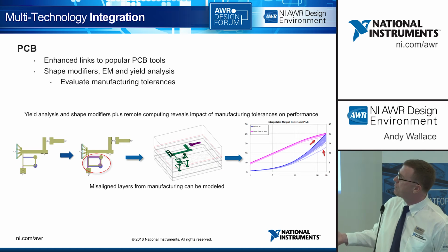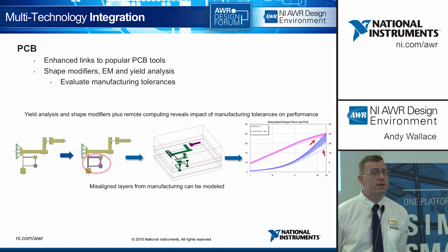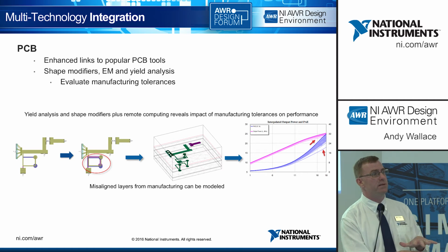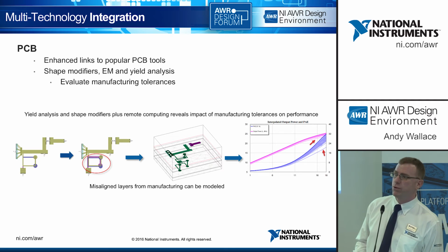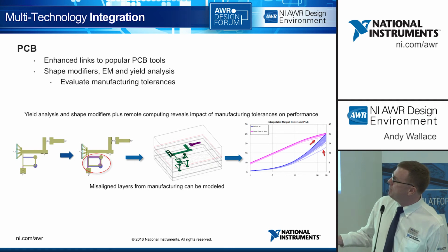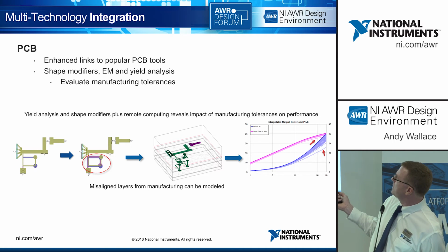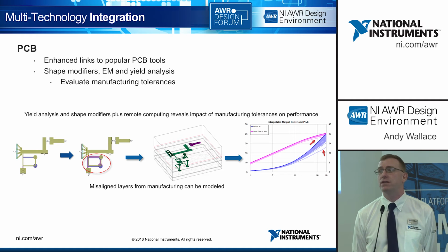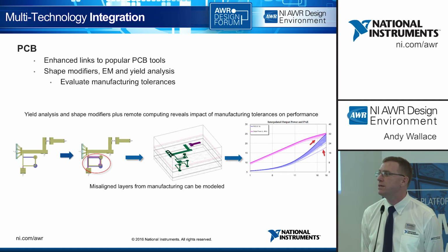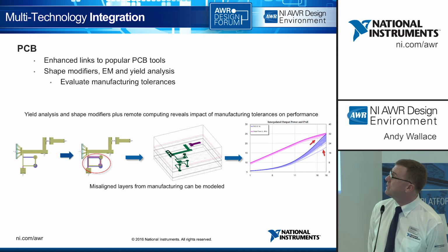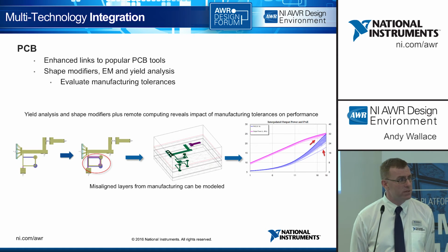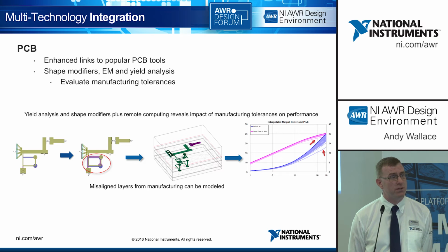So this is an EM design of the front end of a matching network. This is on a multi-layer laminate with this specific inductor through the board layers you can just about see here. And what I've done is with shape modifiers, I've played around with the registration alignment in the processing, the manufacturing stage, and asked it to go through and sweep that registration, give me multiple EM simulations. You can see it offset here, the layer registrations of that spiral, and of course generate the results in a yield data type format to show us the spread of a likely production across that, but this is whilst running EM simulation. About the best results you can get, but also taking into account manufacturing.